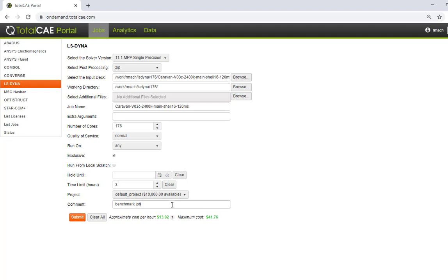Now we are able to have a wide variety of post-processing tools. For this particular application, we are supporting FemZip, which does application-aware compression, LS Pre-Post, Oasis, HV Trans, and then just Zip. And you can have your own custom post-processing. Just by selecting this button, you can automate it so all the post-processing happens automatically, so you can produce reports, do compression, generate pictures, whatever it is you need to do. We can make the whole workflow end-to-end automated.